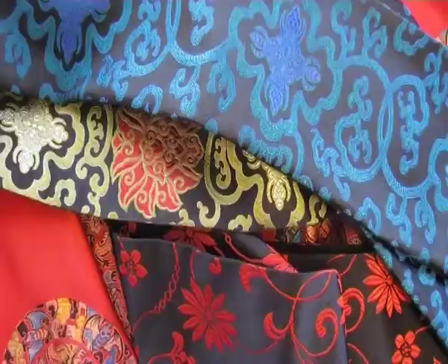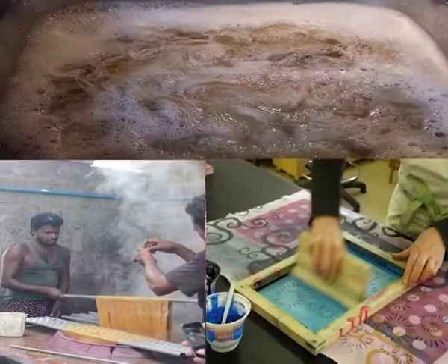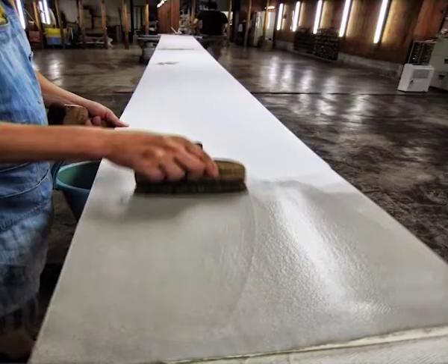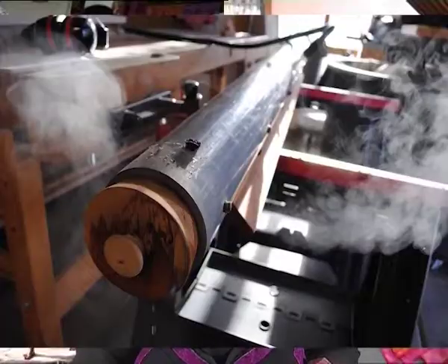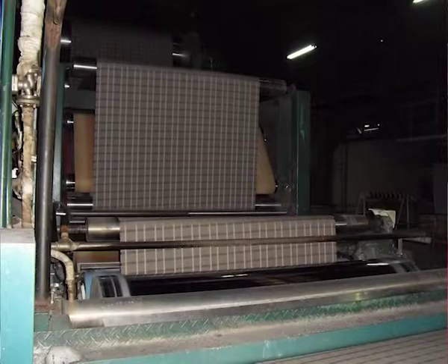Hangzhou plant, one of the biggest in China, processes 1.8 million square meters of silk fabric on an advanced line for scouring, dyeing, printing, finishing. A compound here for continuous scouring, overflow jet dyeing machines process wide width fabrics. For printing, automatic and semi-automatic flow process lines are adopted. Imported machines also handle steaming, washing, shrink-proof treatment and drain batch transportation.